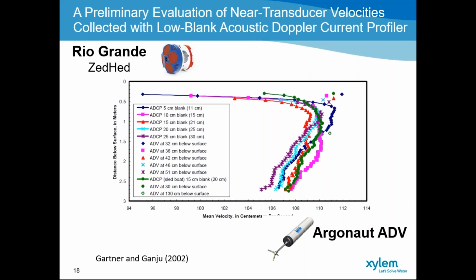As the technology improved and further development was done on transducers and acoustic Doppler instruments, that portion was investigated as well. It is now feasible to measure much closer to the transducers, from the standard 25 centimeters when acoustic instruments were brought out, to nowadays where you can measure up to 3 centimeters away from the transducers.